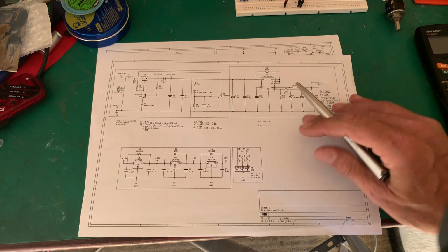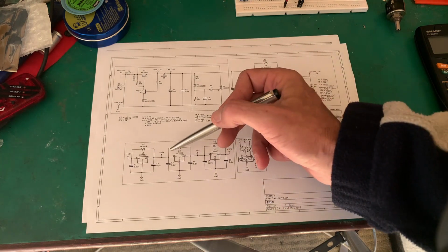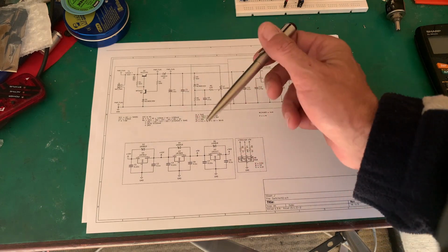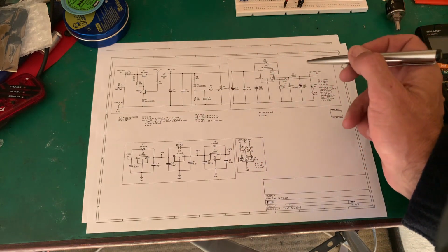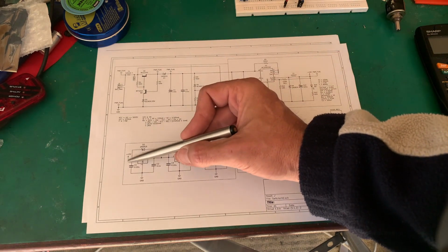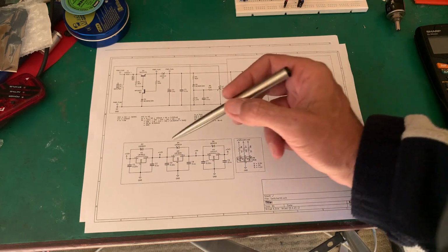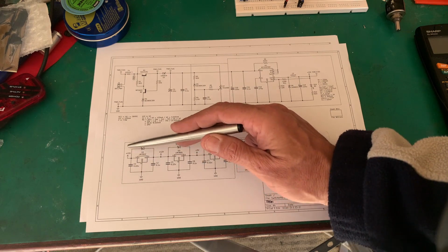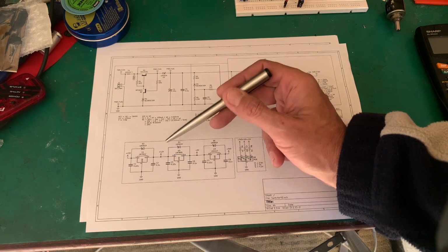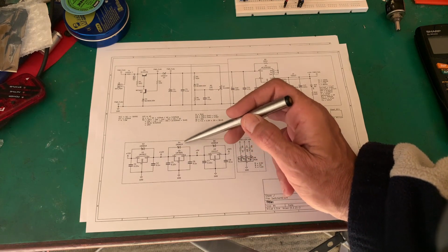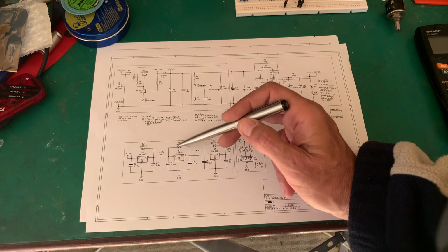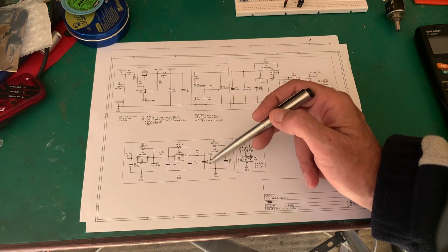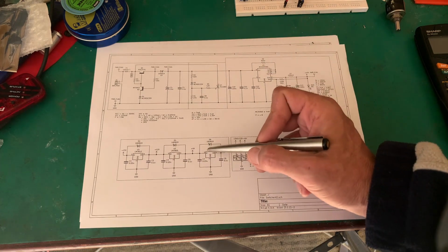And all I'm doing is, we haven't spoken about them, but you can figure out what's in here knowing how an op amp works, but we will do later on maybe a series on that. We have 3 voltage regulators. We have a 12 volt regulator, so our 15 volt comes in, we get 12 volt out. We take that to a 5 volt regulator, and we take it to a low dropout 3.3 volt regulator. Why we are doing that, you will see as we go along.